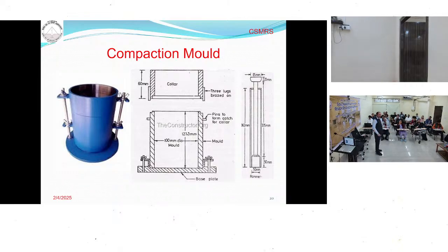When you fill it completely, take out the collar, take out the base plate, and make both ends flat, and weigh it. Determine the moisture content. After that, what do you do? Add some increment of water.